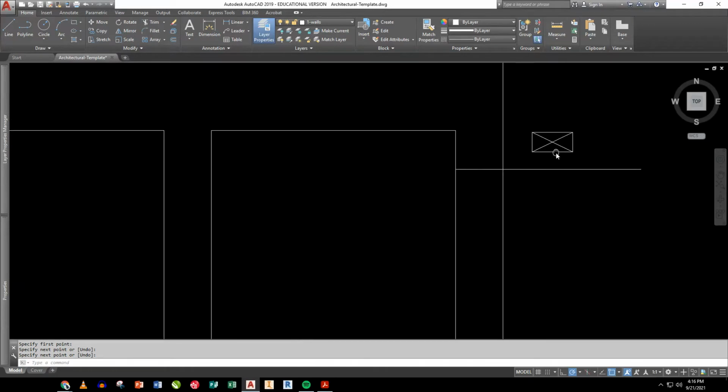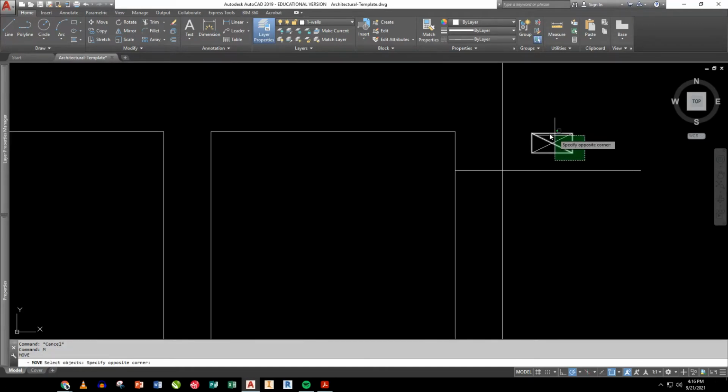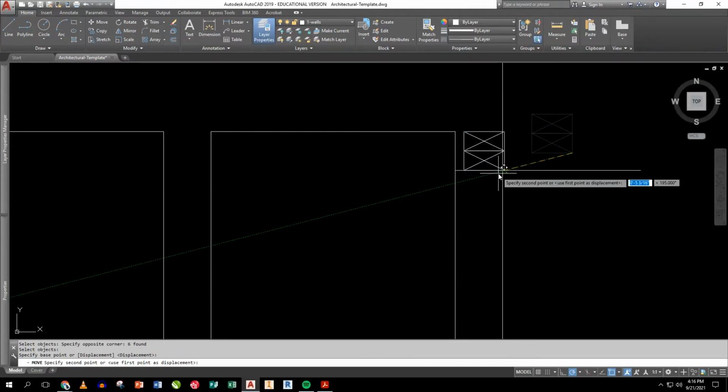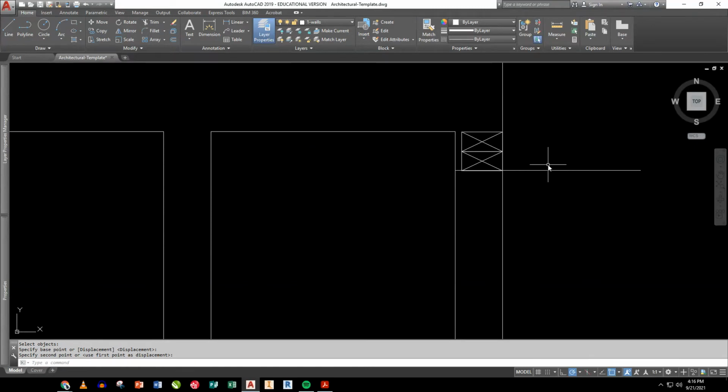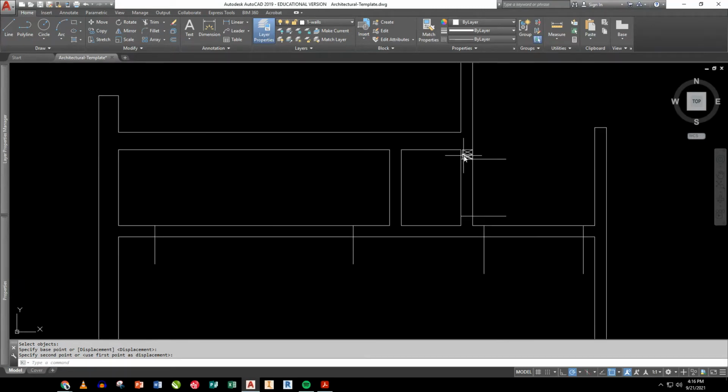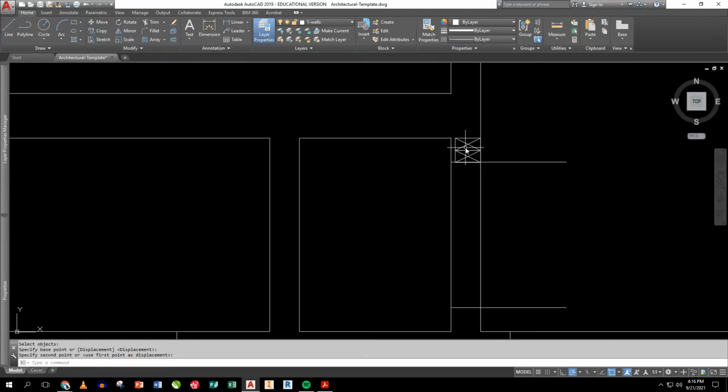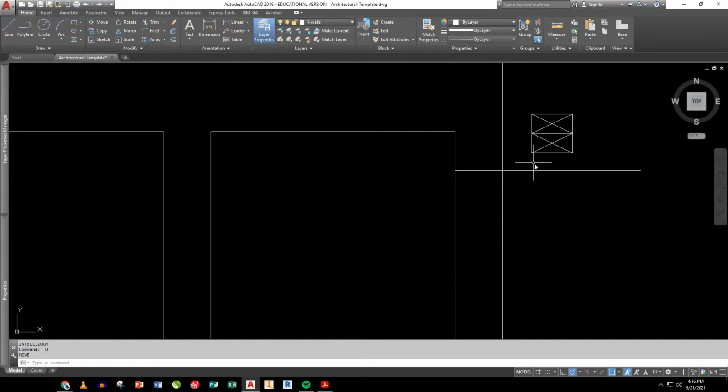I'm actually going to put an X through it, like if you're looking at it in section. To make a door jamb, you actually have to have a trimmer stud that is butted up next to a king stud, and that goes in the wall and sits just about like this. Well, if you don't have the right space, it doesn't work. Does that make sense to everybody? Okay, so undo.